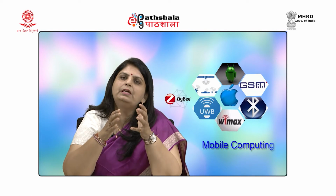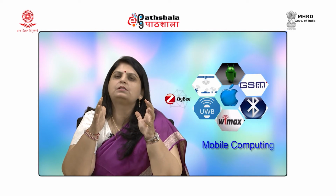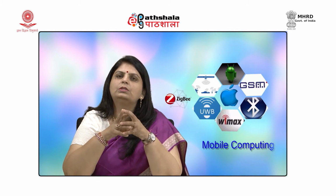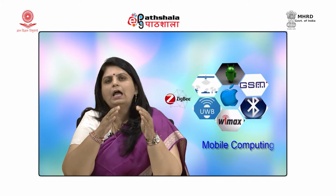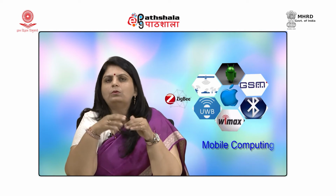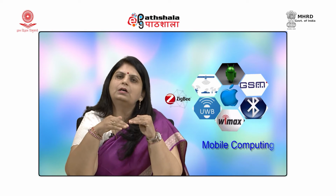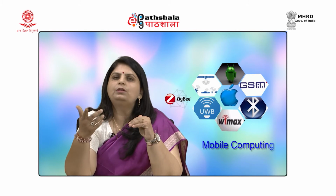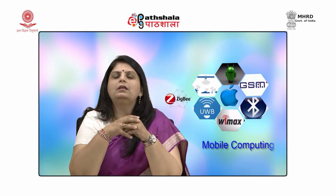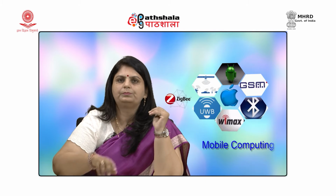So, if the wavelength is more, the antenna size will also be bigger because the antenna size is directly proportional to the wavelength, right. And since the wave is following the ground, these antennas are nearer to the ground as compared to other propagation like space waves, in which the antennas are a little above the ground.